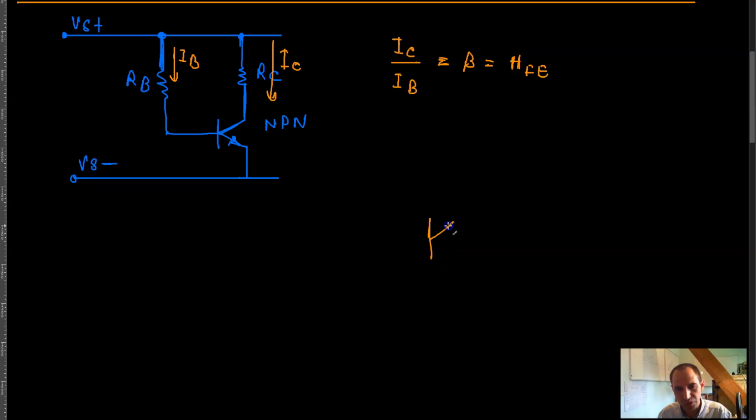Meaning that you can put the transistor over here, the emitter, you give it to the ground, right? And then you have a load over here. Let's say that you have a lamp over here. This lamp goes to the positive supply voltage, right? And the other end of your lamp goes through your collector, goes through your emitter, goes to the ground. If these two terminals are connected, acting as a closed mechanical switch, your lamp will turn on, right?